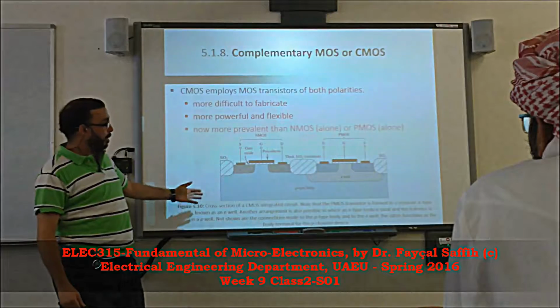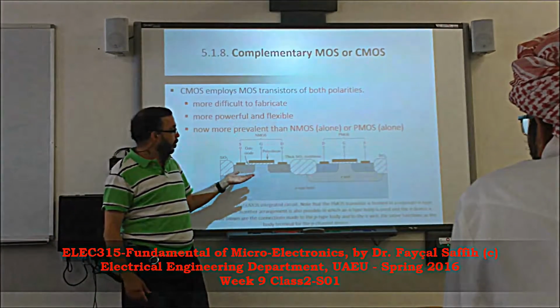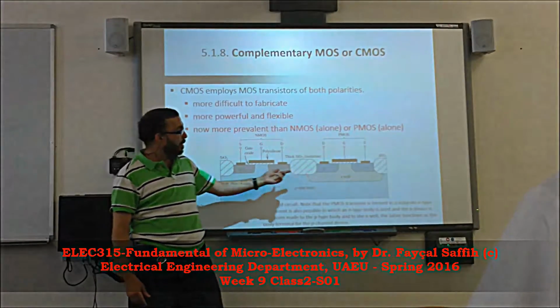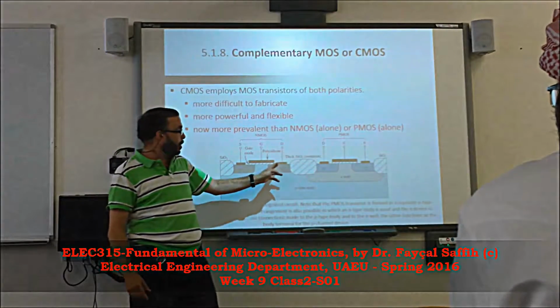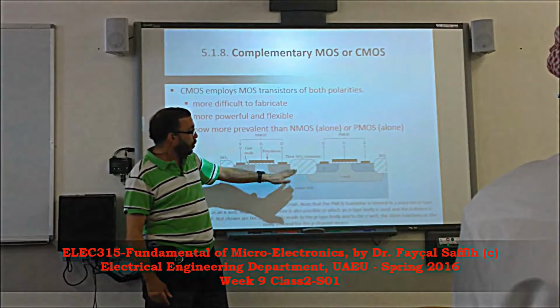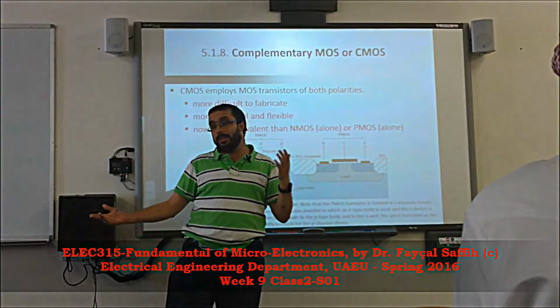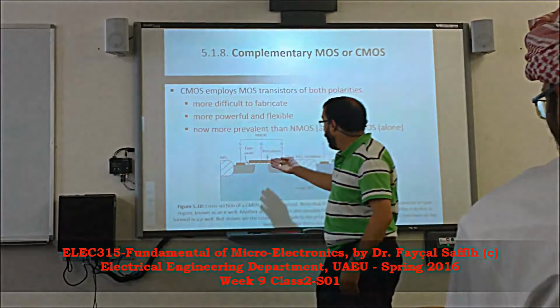In this technology, CMOS, we are able to build or fabricate an NMOS just beside the PMOS. To avoid any cross-link between them, especially between source and drains, we put some isolation. And the best isolators are oxides, like what we have here in the gate.